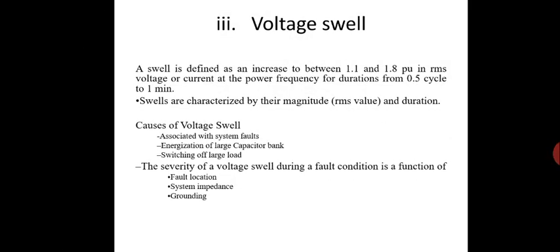Causes of voltage swell: associated with system faults, energization of large capacitor banks, switching of large loads. So it will be largely associated with system faults, the energization of capacitor banks and switching of large loads.